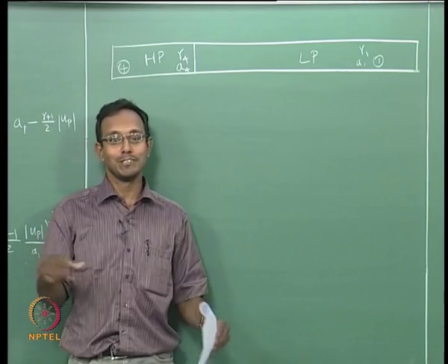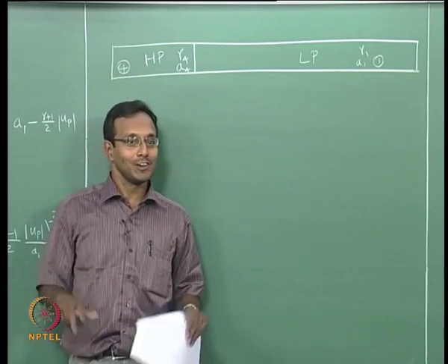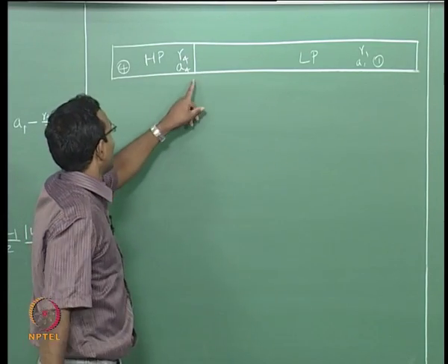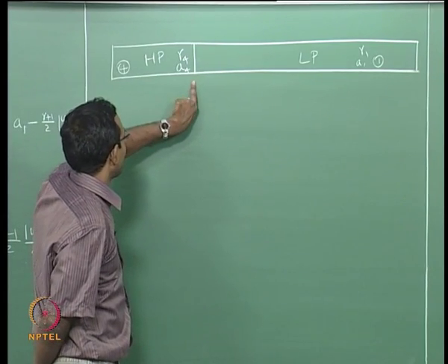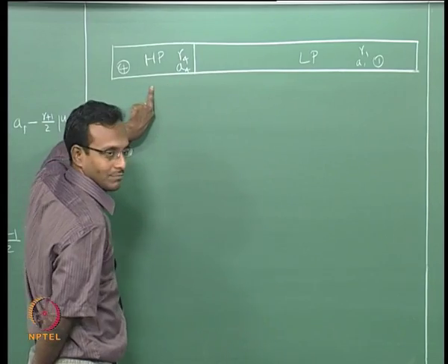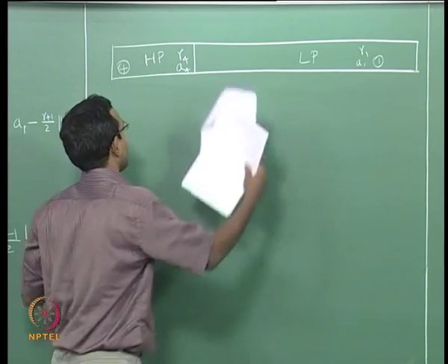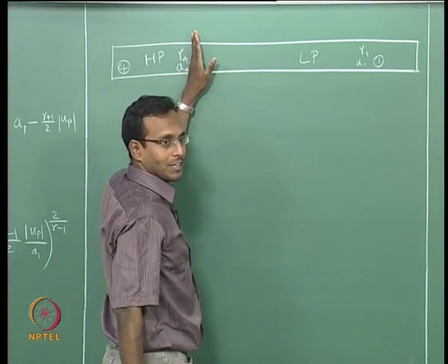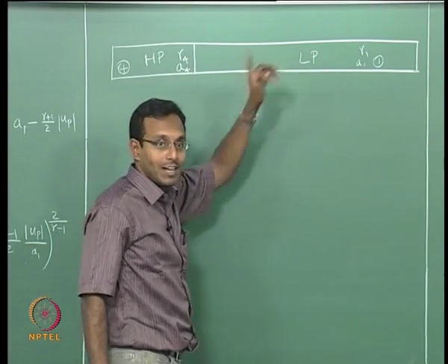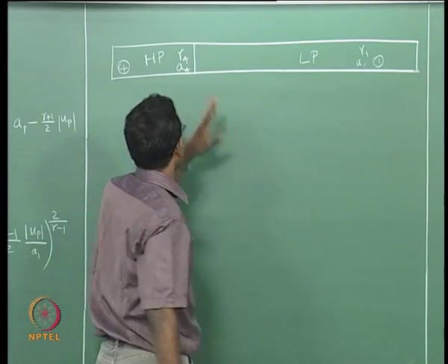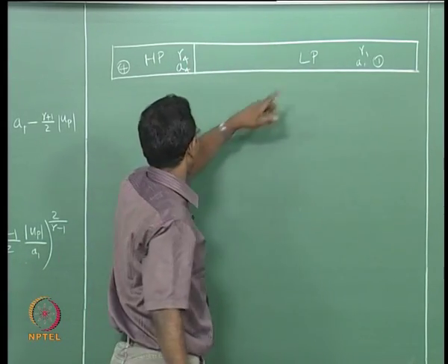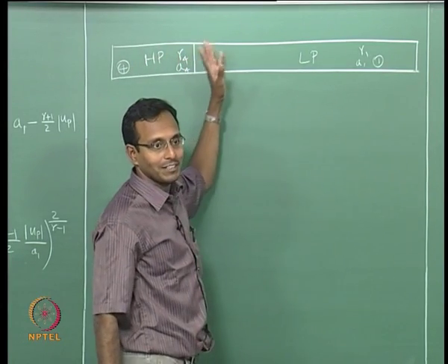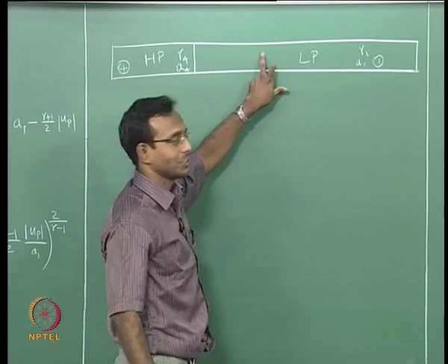And what happens to the outside world if there is some people standing there? They are going to be pushed out more away from the gate. Okay. So what is going to happen in here is there is going to be an expansion wave that will go in this way. If I look at only the high pressure gas section, it looks as if there is a piston that moves out at some speed, I do not know what speed as of now, such that that expansion waves will keep traveling here and making things adjusted to the other section.